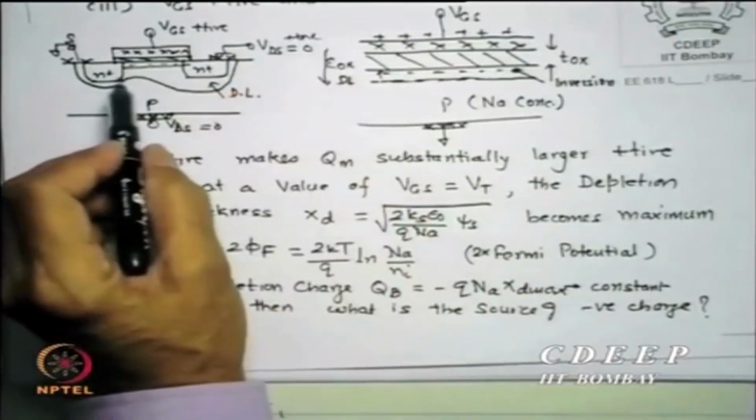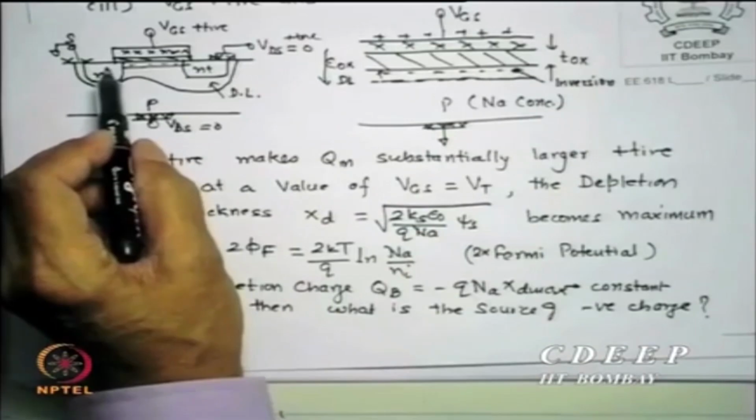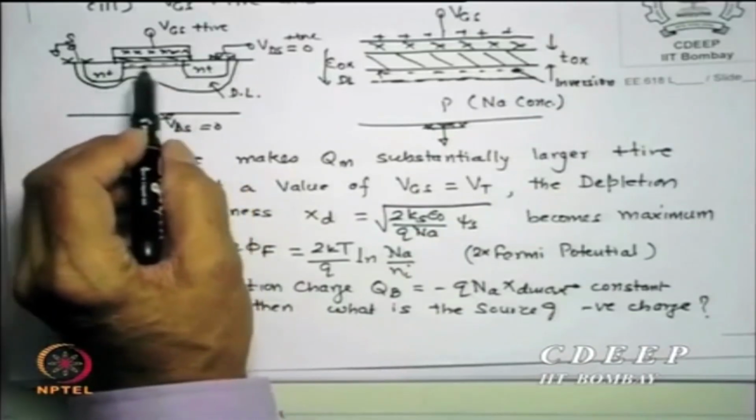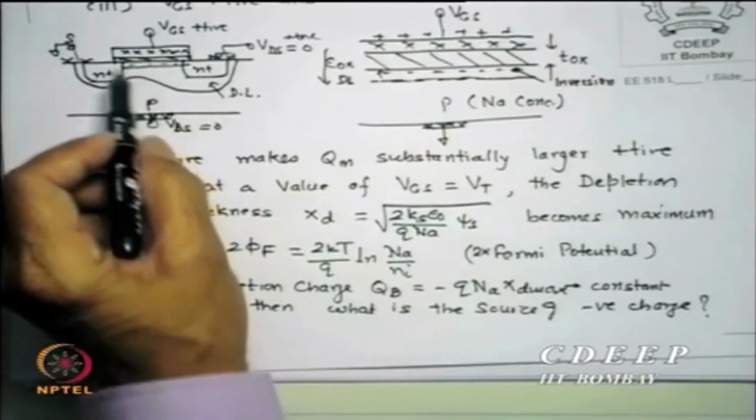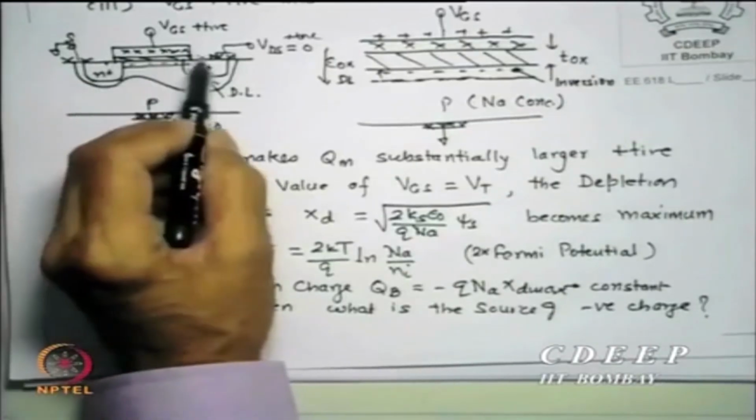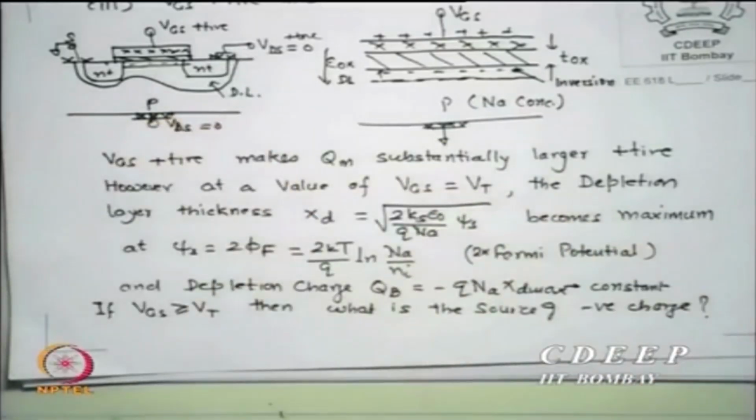This is like a resistor, an N channel, an N area like a semiconductor N bar, with some conductivity. This is source grounded, this is drain at positive voltage, like a piece of semiconductor with two contacts. What current will flow? Ohm's law, V is IR, depending on the R here, current will flow. So a MOS transistor gives you a current which is proportional to V, which is very interesting.